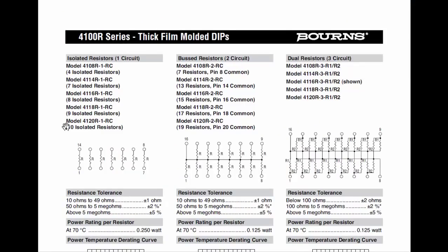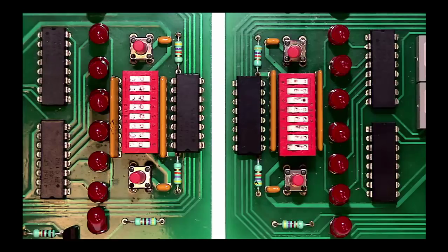This is the datasheet for the DIL resistor networks. You can see that they are pass-through on pins on opposite sides of each other. As all of the resistors are the same in the package, if we placed it in backwards, such as the example on the right, there will be no electrical consequences. The only consequence is the aesthetic look of the board.